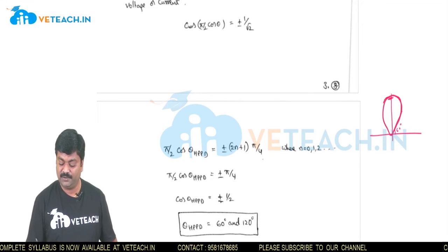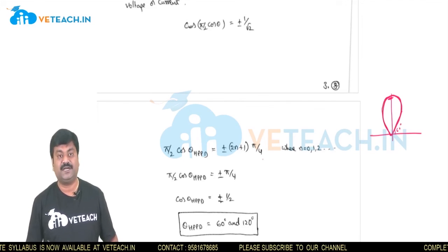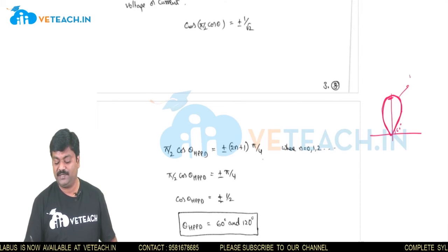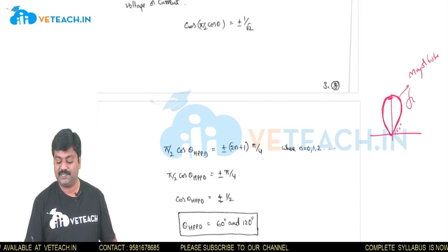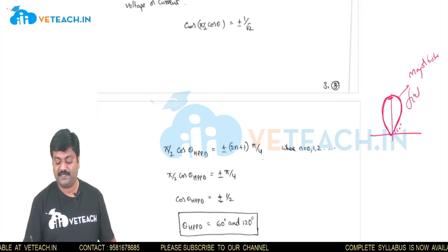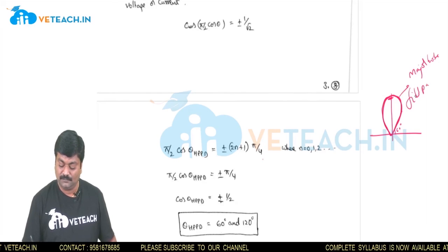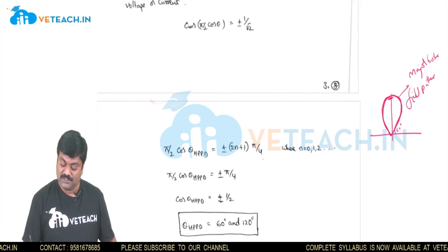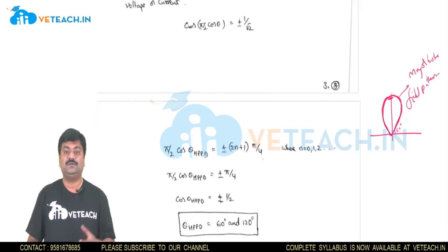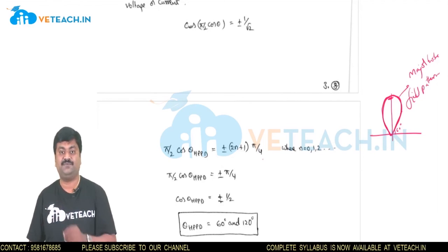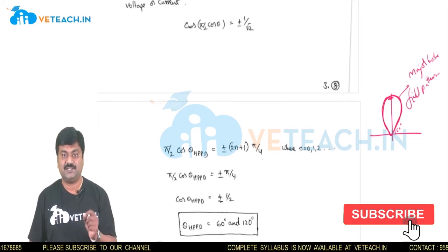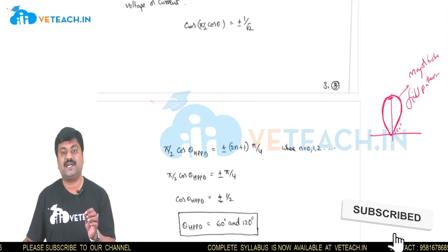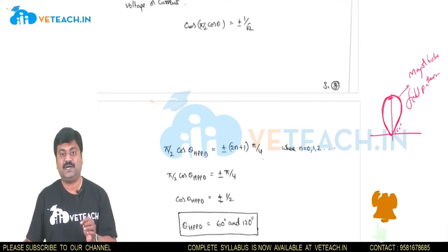If I draw it in that way, I will have this radiation lobe, which we call the major lobe, and it defines the field pattern. In this way, we define the radiation field patterns for an array of two identical isotropic sources which have equal amplitude and phase.